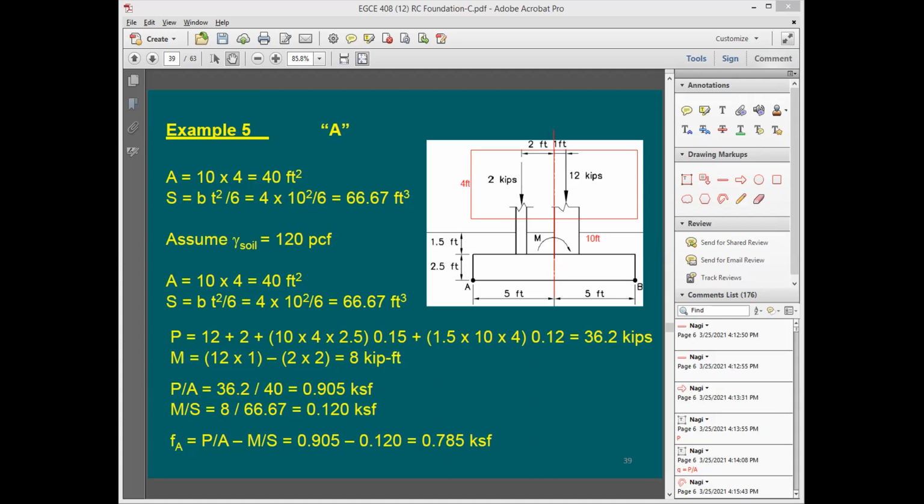I mean, what does it do? It increases axial load capacity for the column. Okay, does it also increase the strength of the concrete? Or it does not? No, the strength of the concrete's already set based on the mix design. Okay, does it increase the strength?